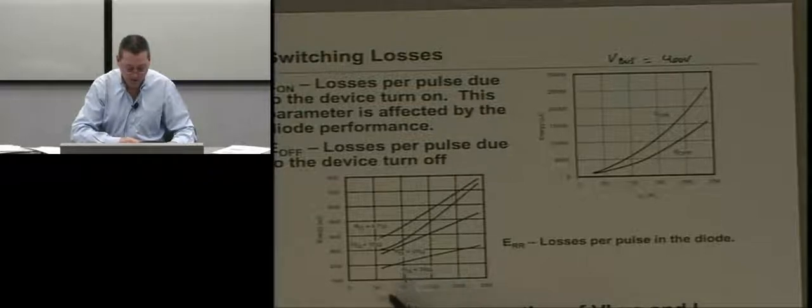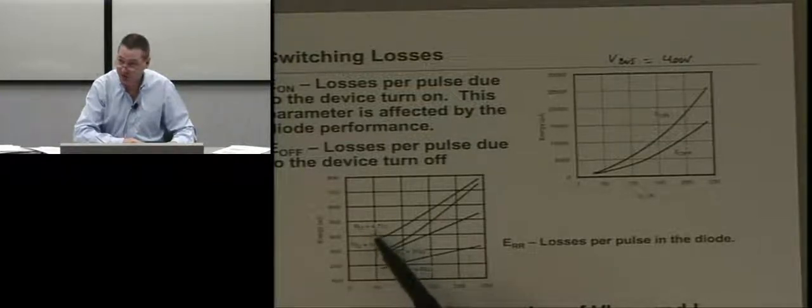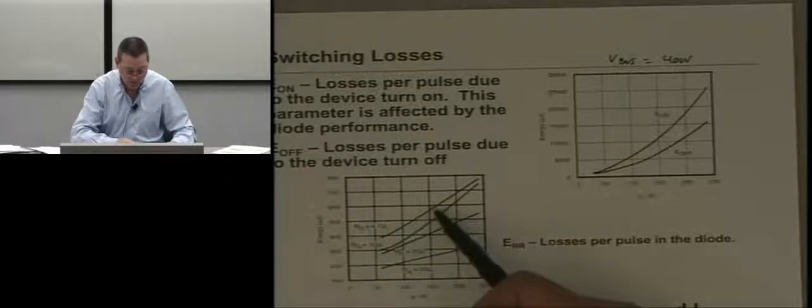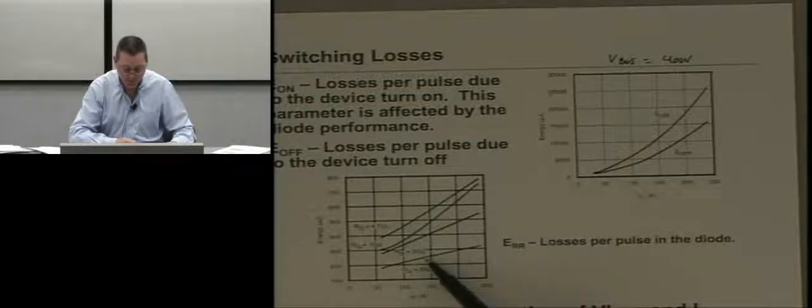And then this is just showing other parameters, for example, as you change the gate drive resistor. In other words, at an RG of 4.7 ohms, you have higher losses than at 50 ohms, which might seem confusing, but it has a lot to do with the diode reverse recovery. As you drive harder and harder, you end up with losses showing up.